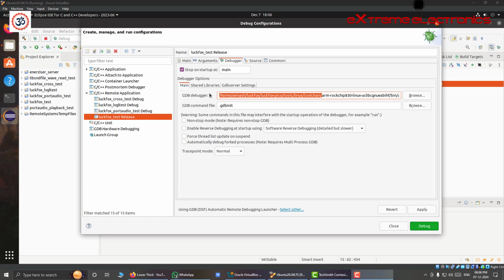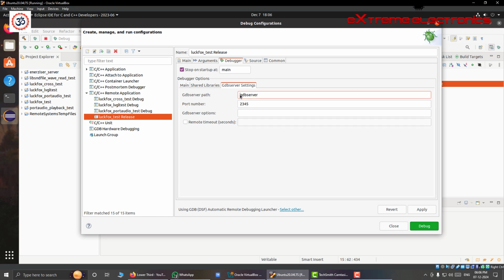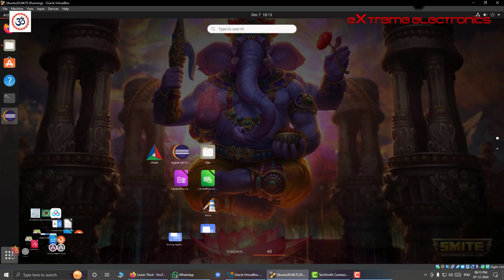After properly configuring the GDB, we will move on to the GDB server setting. And this is the GDB server program. This GDB server runs in our target, and this is native to the target, so it will not have any prefixes. Generally all embedded Linux board vendors install GDB server on the target board by default, but let us confirm this fact. Start PuTTY